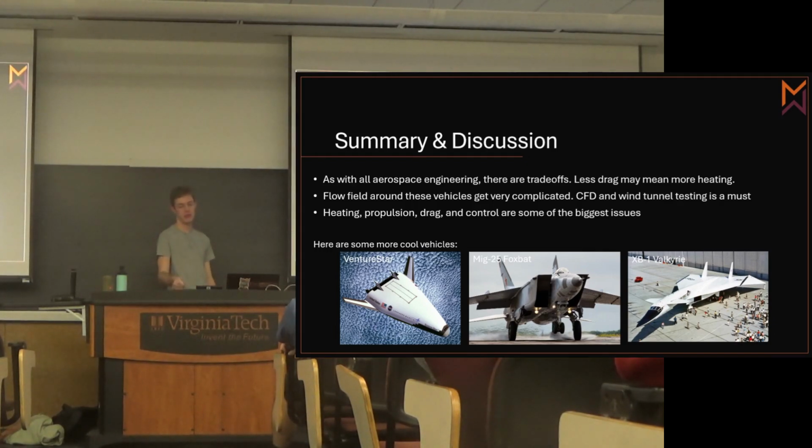So you can see you can't really emulate hypersonic flow conditions in wind tunnels unless they're extremely expensive. And even if they can, they're only giving you a tiny aspect of it. So one common type is you're putting in a very specific gas and heat, and you're trying to emulate only the heating. And the one I was talking about where they cool down, maybe they're just trying to figure out what are the shock directions and interactions. So you can only get pieces. So that's why CFD is a new big part, which I advertise because that's what I do.